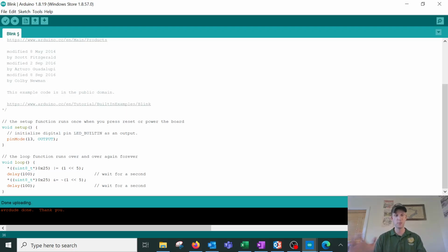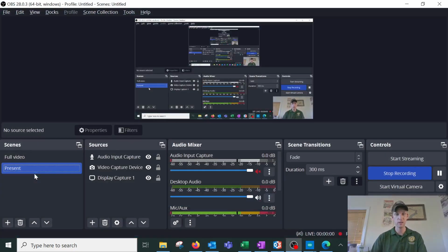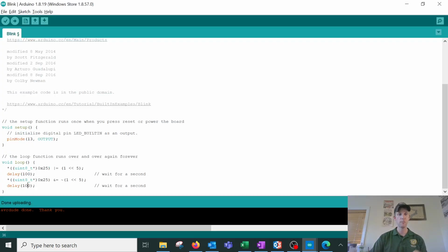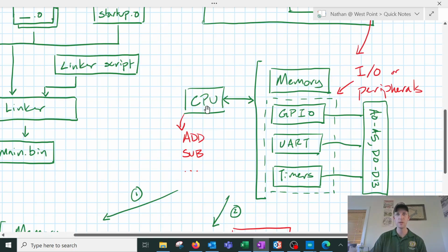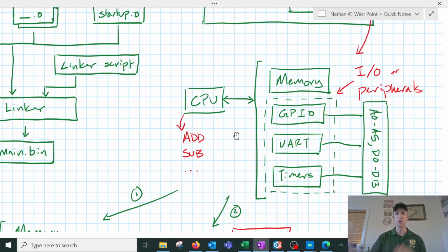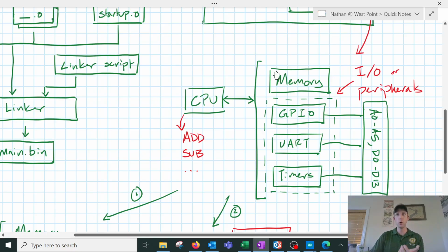And so hopefully that proves that, with digital write, there's nothing fancy about the Arduino IDE or what's going on in this microcontroller. What it amounts to is this processor being given simple instructions, which include reading and writing from memory locations that are also mapped to these peripherals. And I can get my microcontroller to do useful things by writing code that reads and writes from these peripherals in useful ways. So now I've got the question: if I've got a program like this little Blinky program that I want to execute, how do I get that code into memory in the first place?